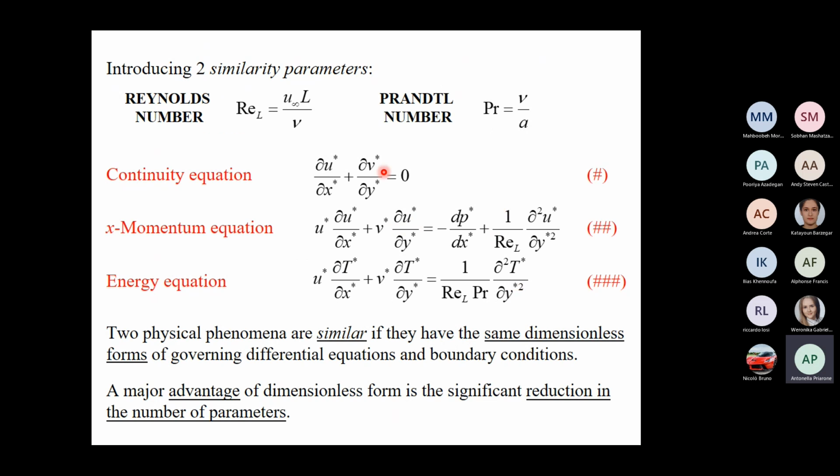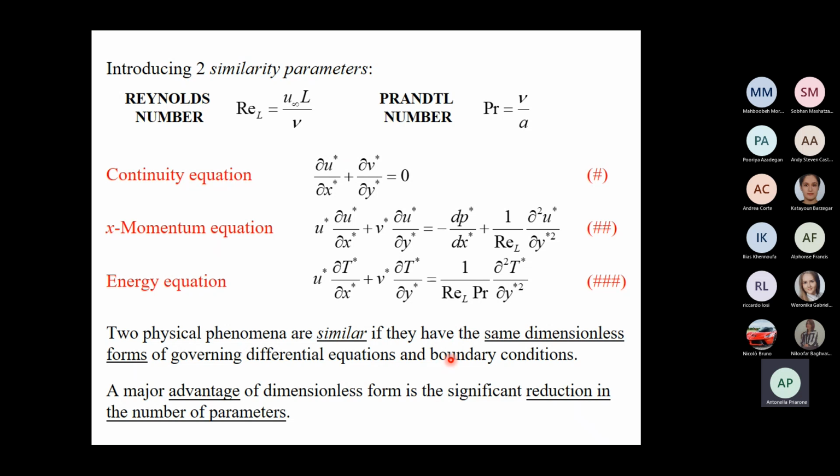These are the equations that finally we will obtain, that are absolutely similar to the previous ones, but involve dimensionless numbers, in particular the Reynolds number and Prandtl number, which is the advantage of writing the equation in this way. Because writing the equation in the dimensionless formulation allows us to create similarity among different cases. Now I'm trying to find simpler words to explain this point. That is not simple.